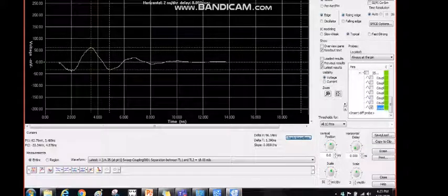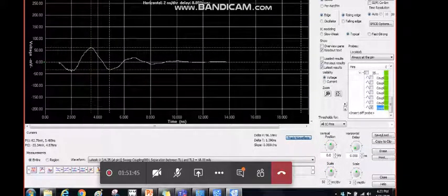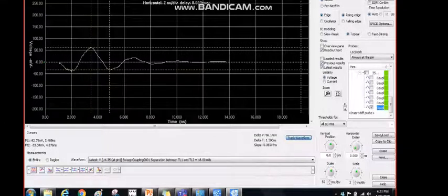Sure, we can surely look into such requirements specific to differential pairs. But as you shared, you're working with high speed, in the order of 10 gigahertz. That requires a lot of advanced understanding of electromagnetic fields, and there are no 2D solvers which can give you results closer to practical simulations.